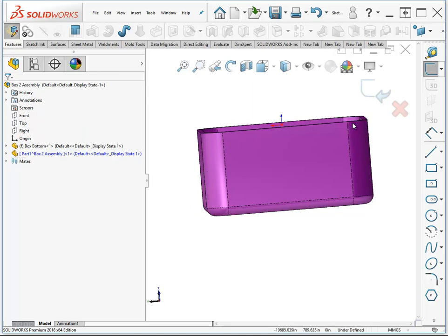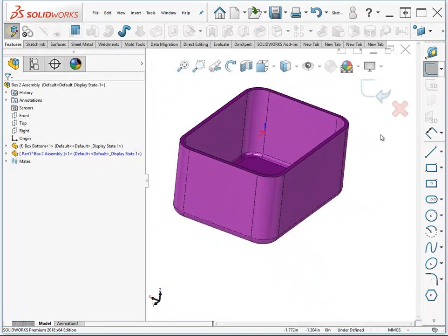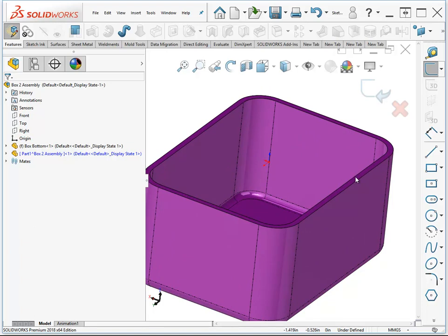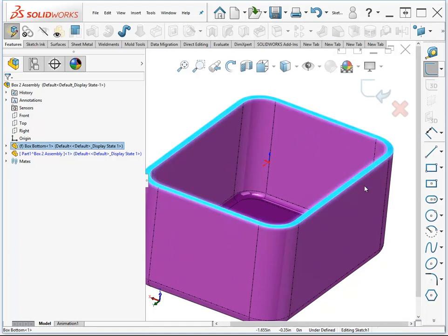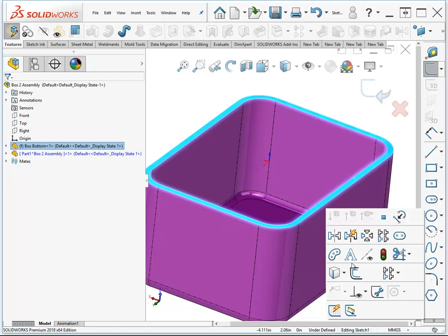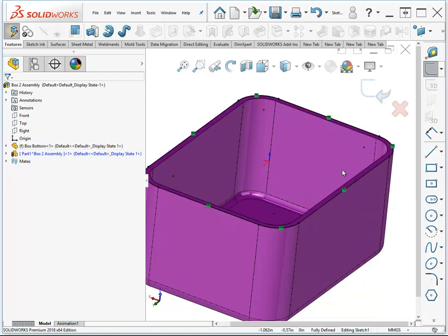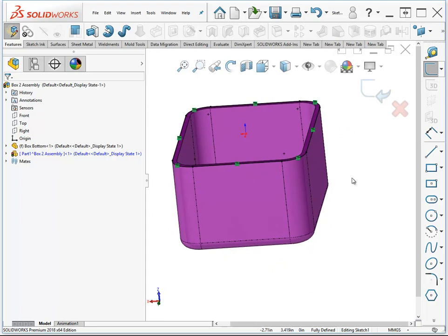Okay, so the first thing SolidWorks does after I select the plane is it kicks me into a sketch. And here's what I'm going to do. I'm going to select this face after all and use my convert entities to get that edge that goes around. Now I'm going to do something that might surprise you here.